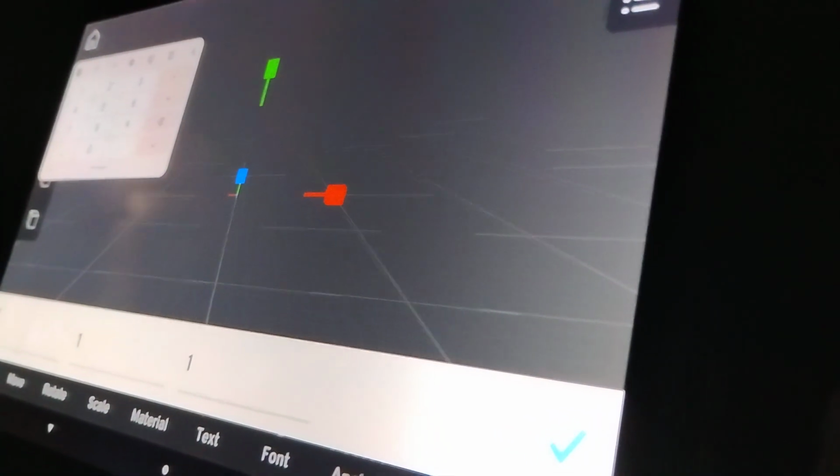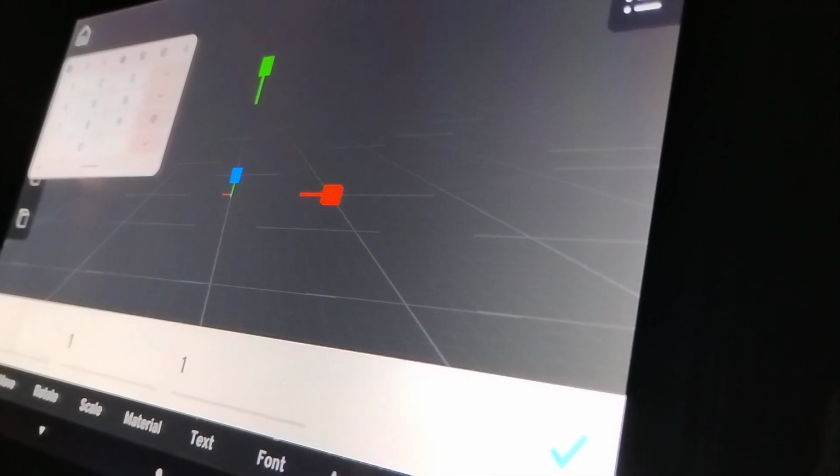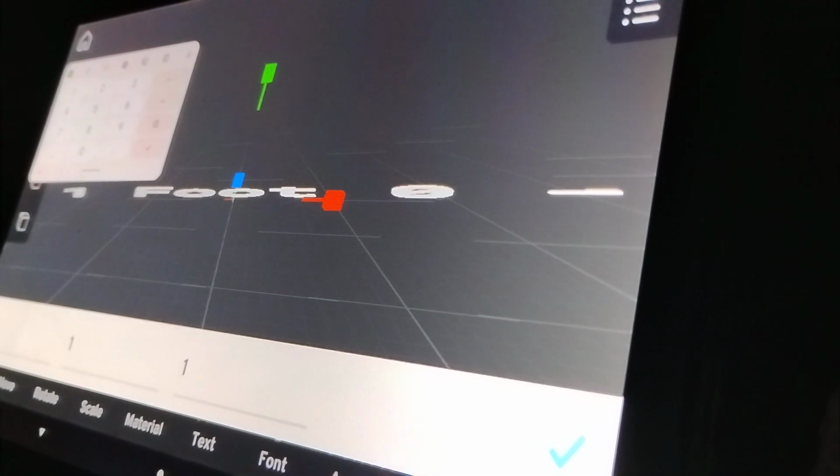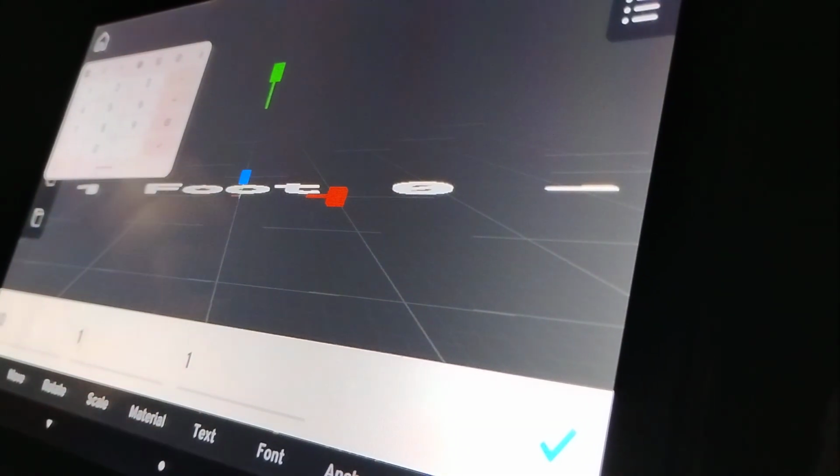If you do scale first and then try to do these numbers, it'll revert back to the default, and if you try to change it, bad things happen. You have to delete the text and start it from scratch. So the last thing you do when you're creating text models in version 3 is scaling.